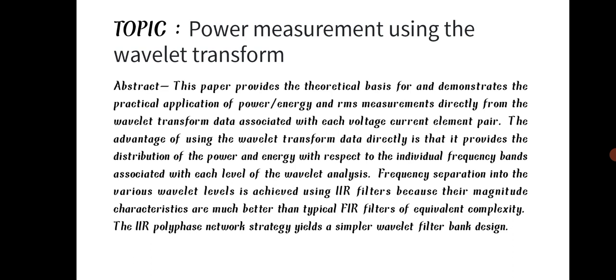This paper provides the theoretical base and demonstrates the practical applications of power, energy and RMS measurement directly from the wavelet transform data associated with each voltage-current element pair.